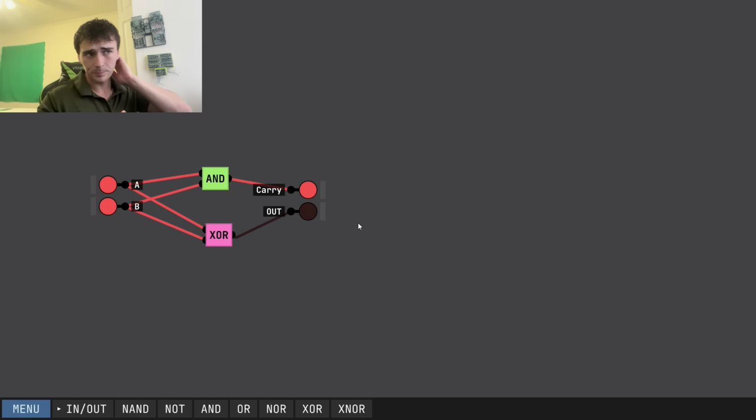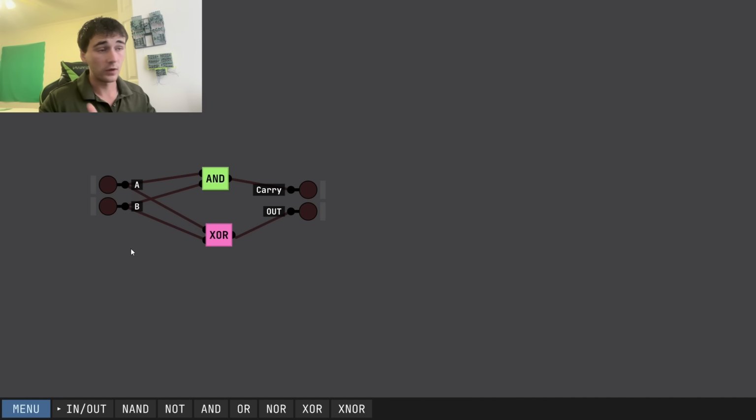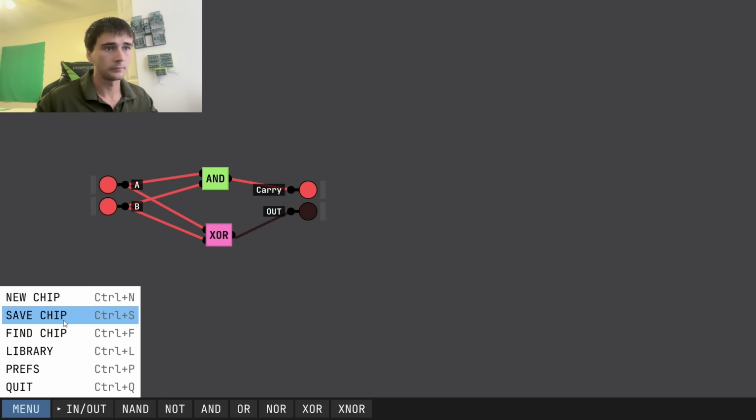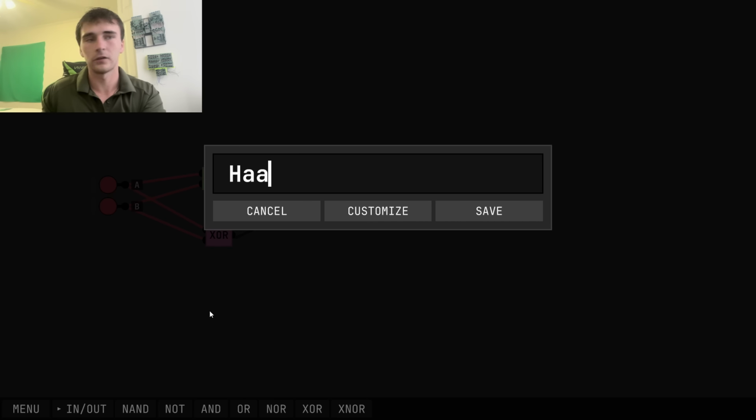So in binary, you can watch my actual adder video for more clarification. But in our base 10 system, when we add numbers and the number goes over 10, we have to carry the 1. But in binary, if the number goes over 1, we have to carry the 1. So that's exactly what we're doing here. So 1 plus 1 gives us 2, which would light up this gate so we can carry the output kind of going forward. So this is called a half adder.